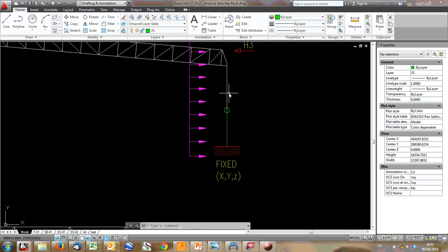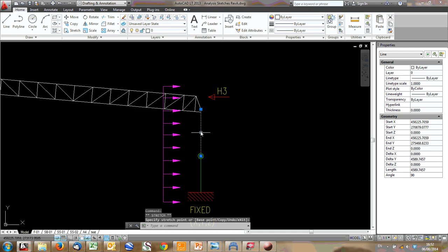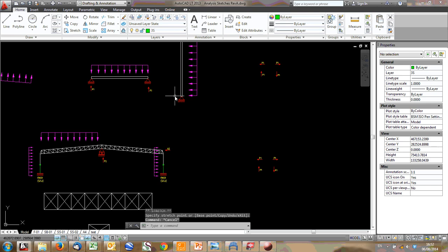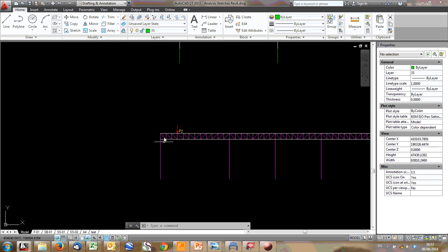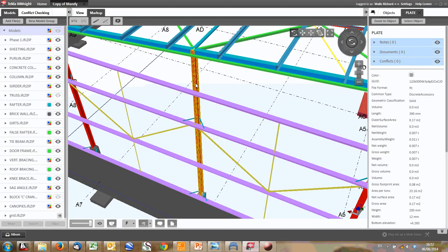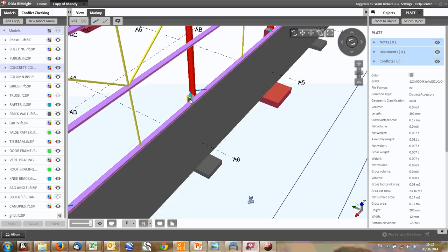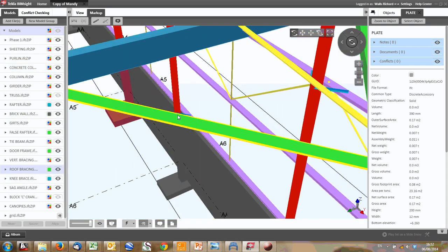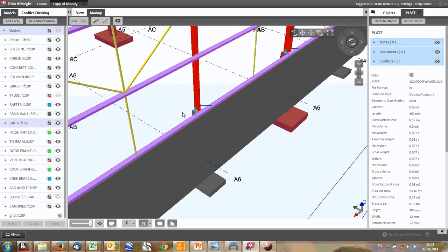The model we've just looked at, the simply supported beam, is this section here. It's actually not on this face, but on the other face. It's on this face along the gable edge. This column here, going up, going down. So here, the load will be carried by a cantilever. This concrete column you can model as a cantilever. It's fixed at the bottom, and pinned at the top or free at the top, with a horizontal load, which is the reaction from that. And that way you can size the column and size the base without too much difficulty.